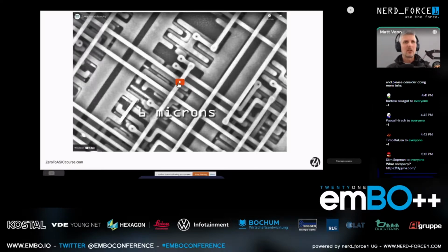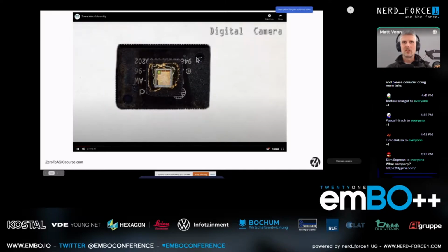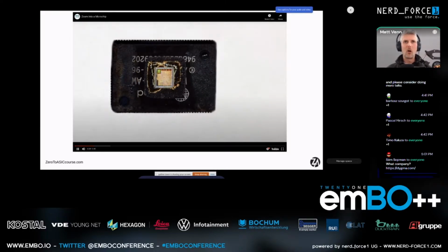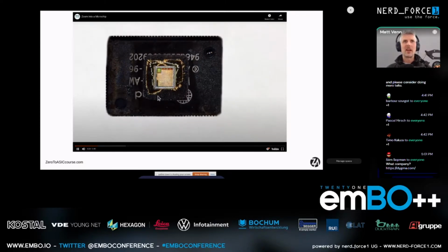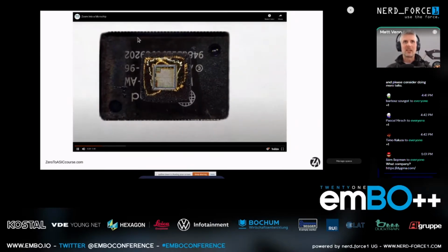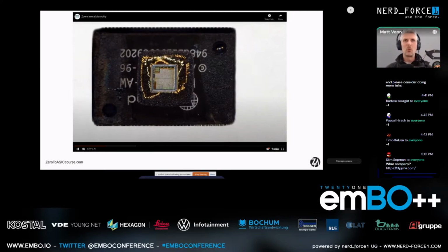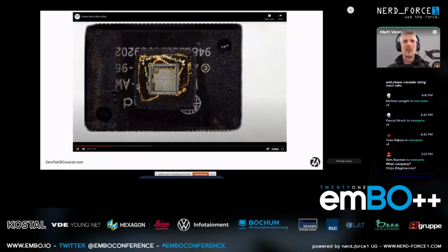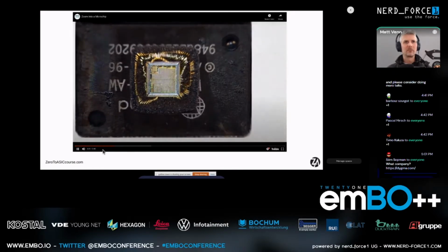Here's a little video of a zoom in. When you get a computer chip, it's encased in a blob of epoxy. If we erode the top of that off with some horrible nitric acid or something, we start to see the actual die, which is a lot smaller. So we have this big package to make it placeable by the machines that run on assembly lines, but the actual working element is usually much smaller than the package. And then we have these gold bond wires that come in from the outside to bond to the pad ring.